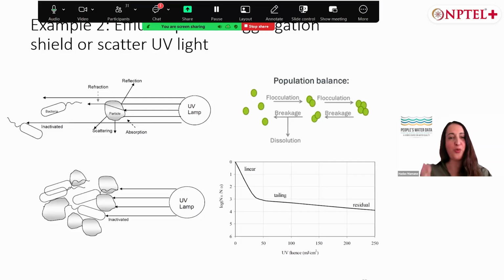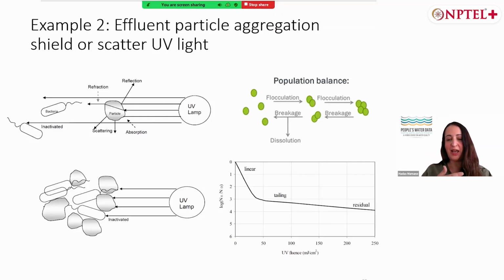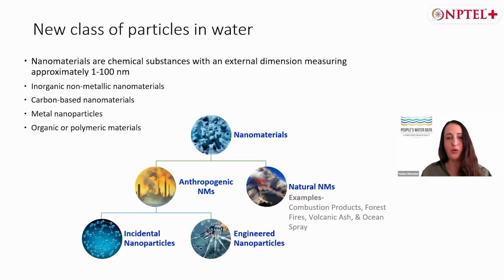And another also important comment is that most of the papers actually take a water sample, they filter the water, and then they examine, for example, the breakdown of micropollutants in water or trace organic compounds. But if we remove the particles and use only this content from the water, we don't obtain the real technology efficiency. And therefore, it's very important to understand how particles impact our water and the water treatment processes.